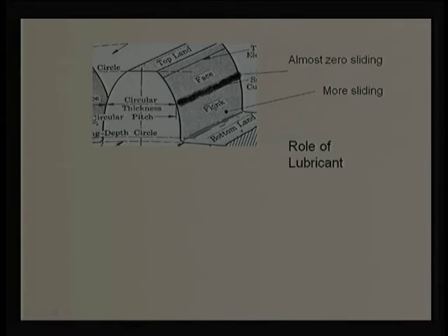Generally, the flank will have a higher wear rate compared to the face. That is why we say that this portion is more subjected to pitting, more subject to failure compared to this portion, and we need to keep a very good thickness of the gear over here.